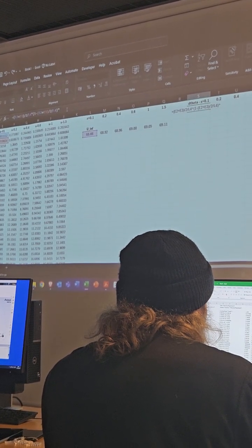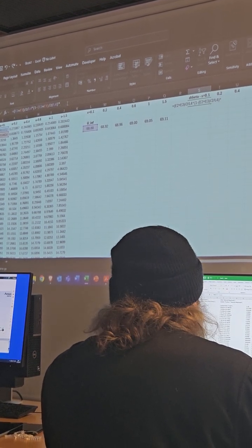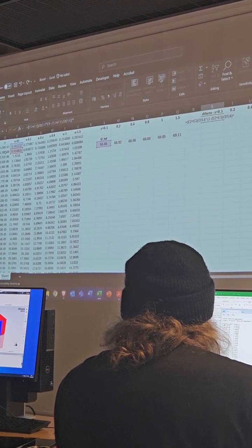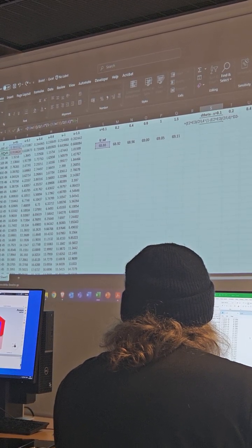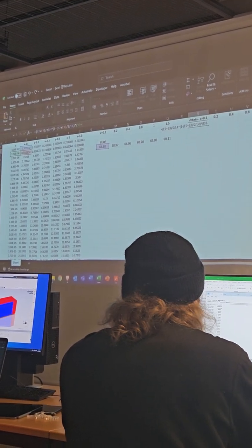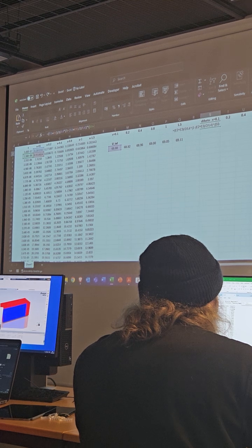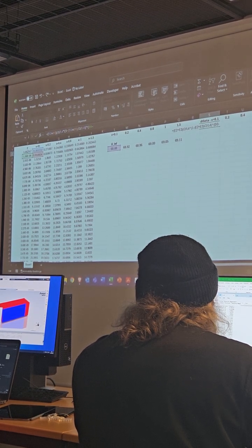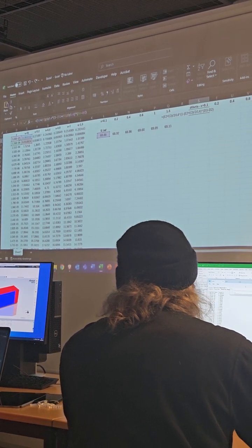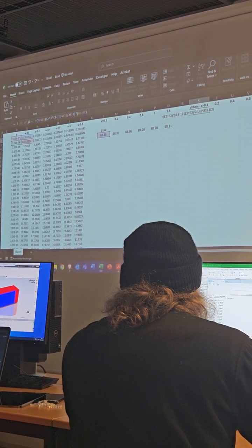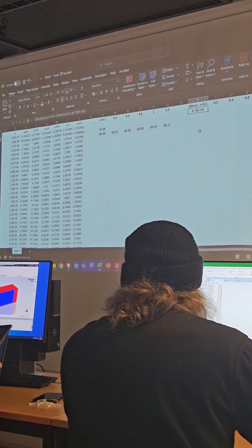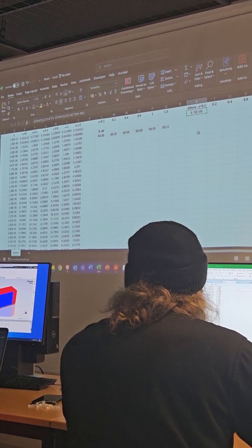times delta y, that is simply the second y value minus, sorry, I'll put a round bracket here. So the second value of y minus the first value of y. So this is the delta y between those 2 points. And enter. So there I get the value of the delta theta, so the momentum thickness between those 2 points.